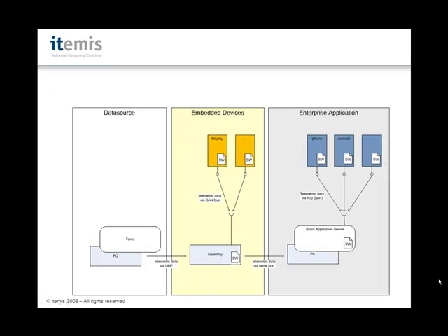The showcase system that we built is an example from the automotive domain. It consists of three major parts: the sensor, the embedded devices, and the enterprise application. To simulate a real sensor, we patched the open source racing simulation Torcs to send out information about the car state. Telemetric data from the sensor is sent throughout the system. It is generated by a virtual sensor within Torcs and sent through a UDP link to a gateway. This gateway is a Blackfin board running embedded Linux.